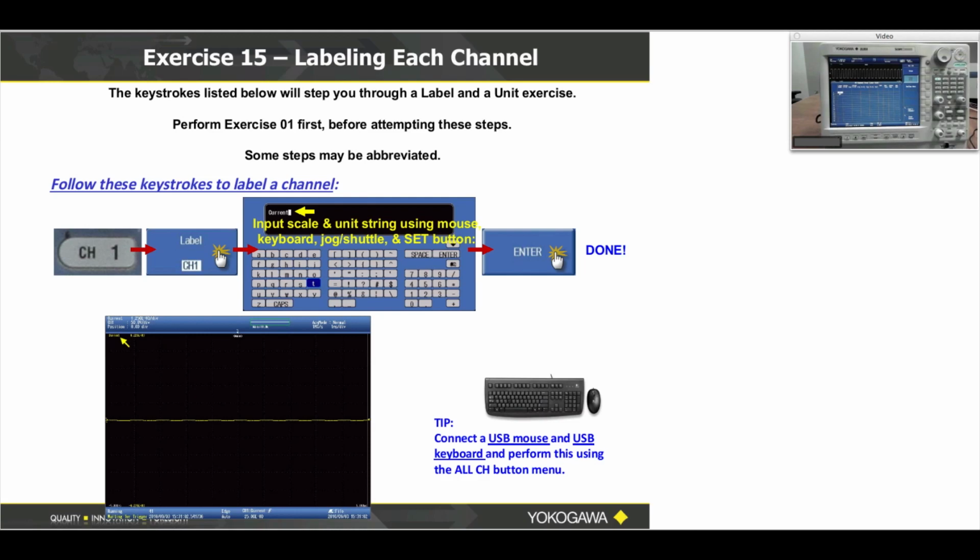Okay, at this time I'll show you how to label a channel. So press Channel 1 button. After you press Channel 1, go to soft menu button number 3, label Channel 1, press that. Go ahead and put your name in this editor here, or you can name the channel after pressure or temperature. This is important. It gets you acquainted with the buttons and the menu layout on the DL850.